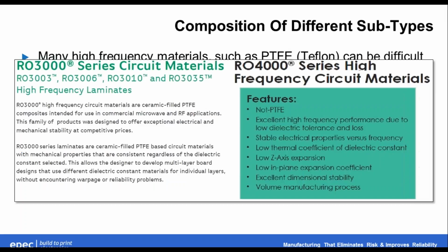So the composition of the different subtypes, again, we have a little blurb on the left here from the Rogers 3000 series. These are ceramic-filled PTFE, and it goes into a little about what the applications are. And then on the right side is the Rogers 4000, which is non-PTFE, and it's for a different group of applications.